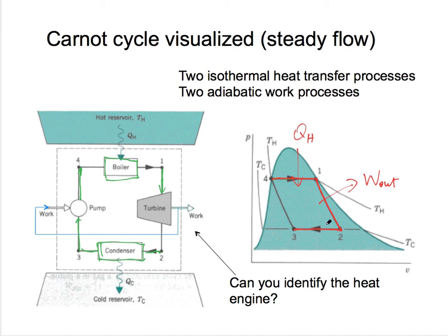In this heat exchanger, heat is taken out of the mixture of a saturated liquid and saturated vapor of water, so its quality further decreases. There's additional saturated vapor becoming saturated liquid in this process. And then if you carefully choose your end point, you come to this point, point 3, and then you let that wet steam go into a pump or a compressor. You can compress it back to its initial condition 4 in an adiabatic process.